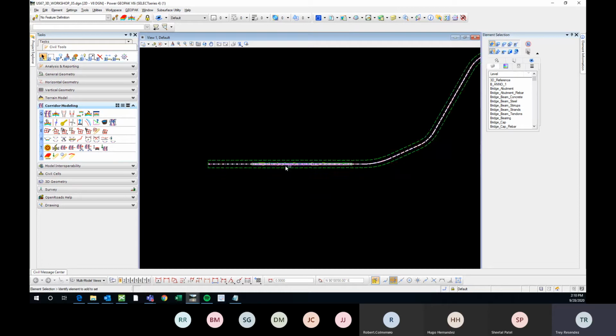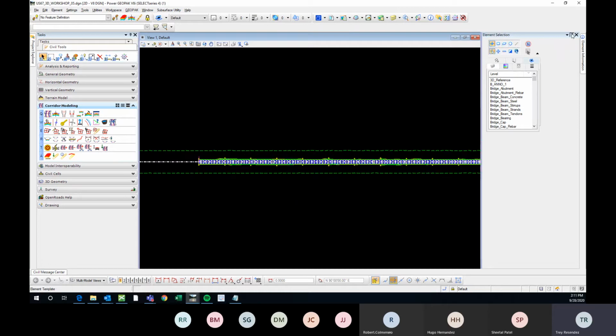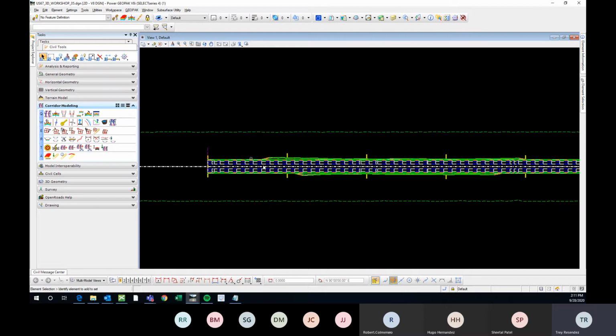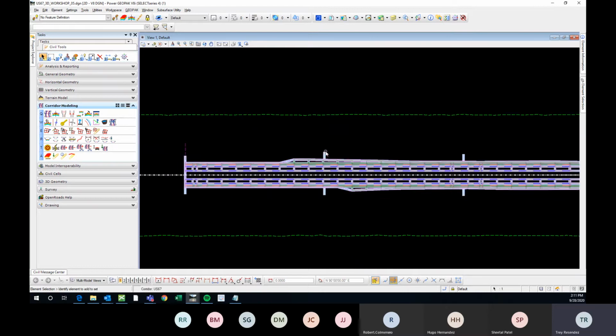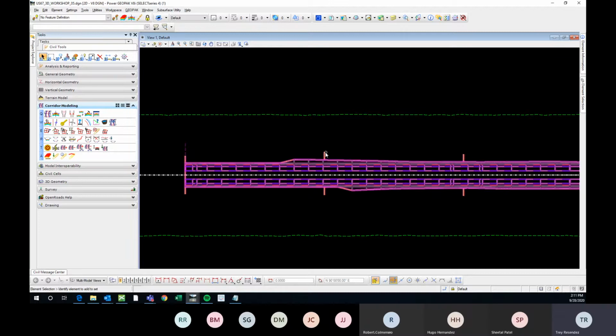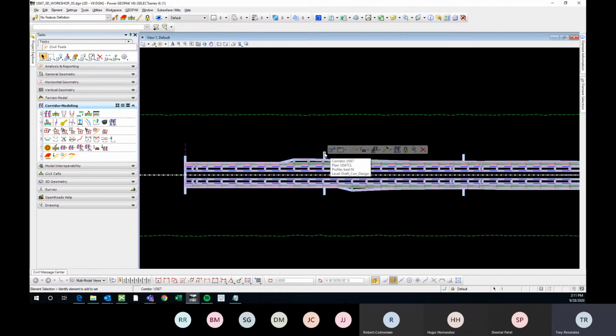And it runs. Now I see my corridor in the plan view, and if I click on this little cursor here and go to properties, then I can see these settings here. It gives me the horizontal, it gives me the profile, and it gives me the design stage. And I can change this, and I usually always keep this to true, because it's going to use the active profile that's attached to your horizontal.